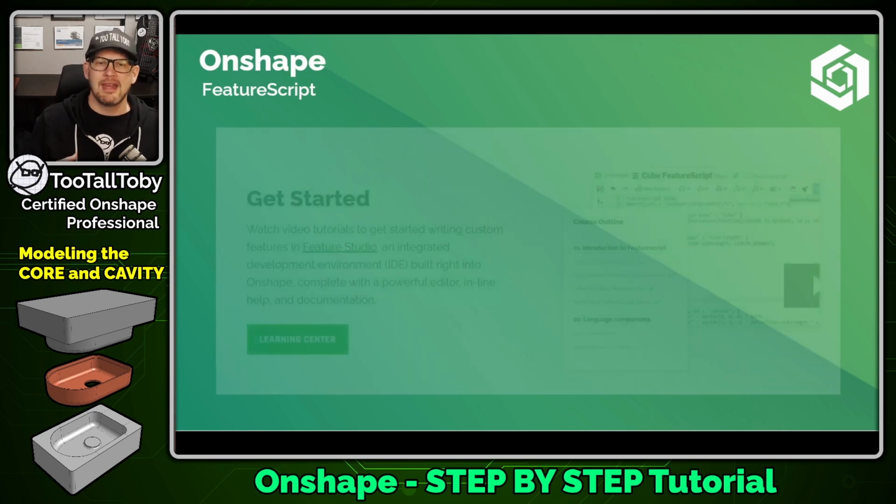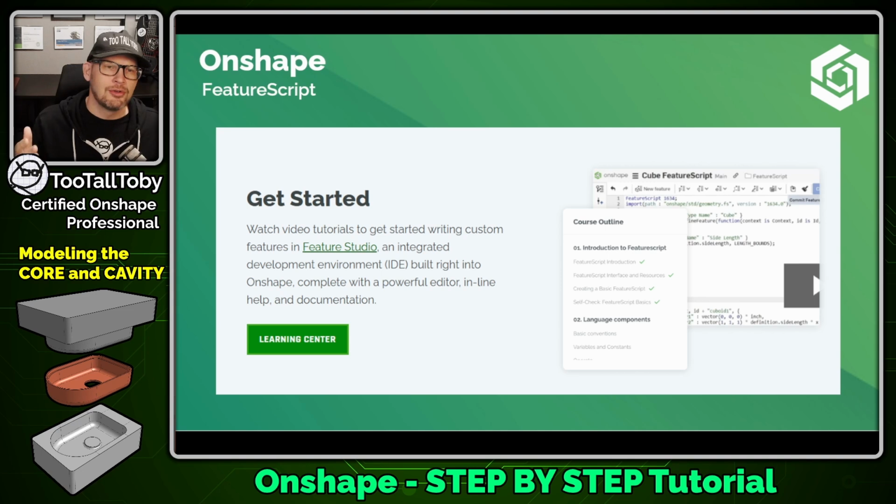And what this means is that you can take a class on how to use FeatureScript. There's a link down below in the description to the Onshape Learning Center. And what you will learn is how to create a new feature that doesn't exist in Onshape. You make a new icon for that feature, it shows up on your toolbar, and you get a feature manager that shows up when you access that tool. So it's exactly like a feature that's already in the software, but it's something custom, something that you came up with that's going to help you solve a problem in your CAD journey.